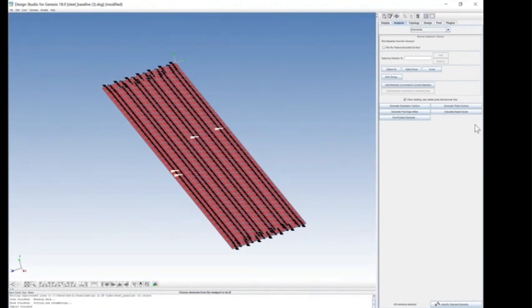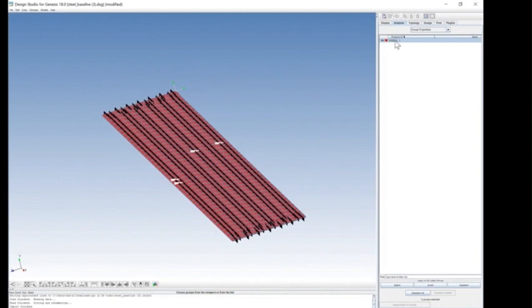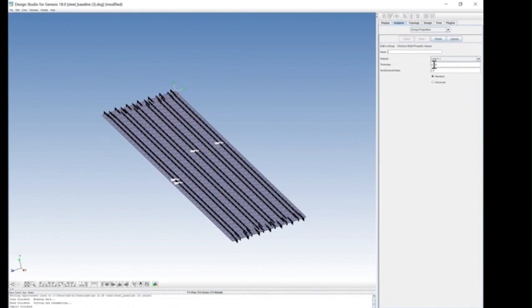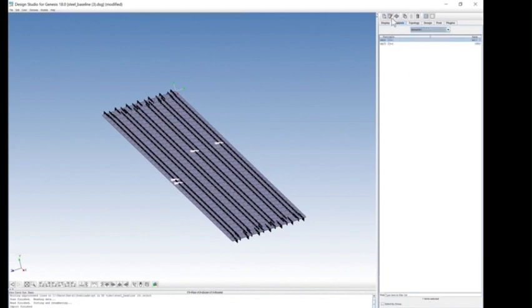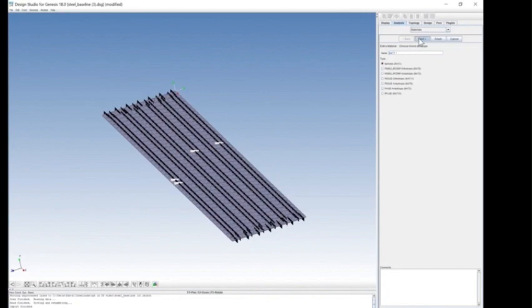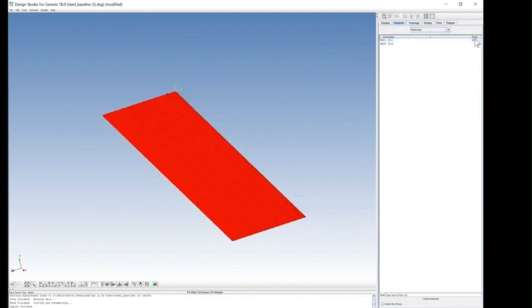However, they're still pointing to this steel material. They're still made from this 3mm thick steel material. And we can check that if we go to analysis, group properties, and they're pointing to this P shell. If we click on edit, we can see that's made up of this 3mm material, and it's pointing to mat 1. We know if we look at our materials and we go into mat 1, that's this isotropic material. There's our material properties for steel. So it's made from 3mm steel, and we can see that if we go to our group properties.